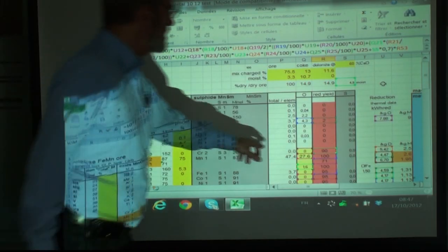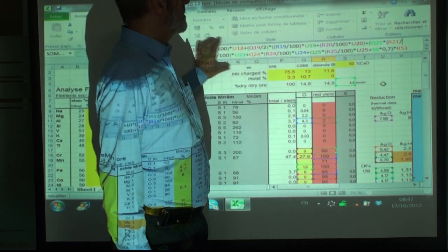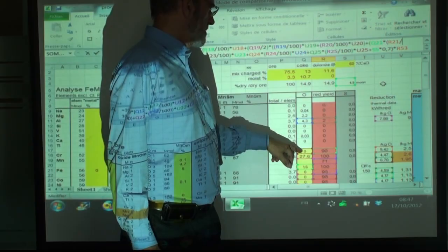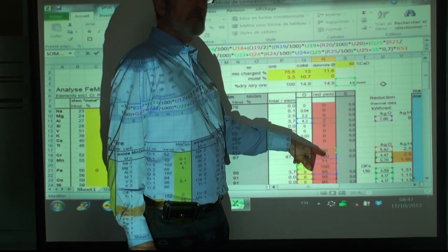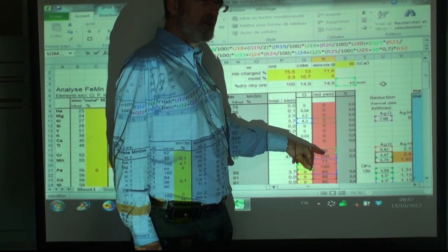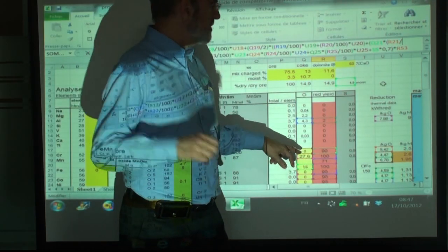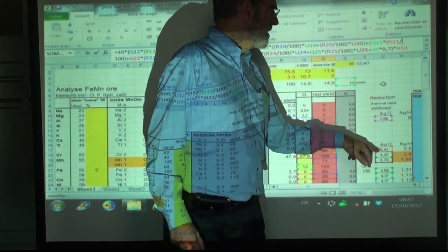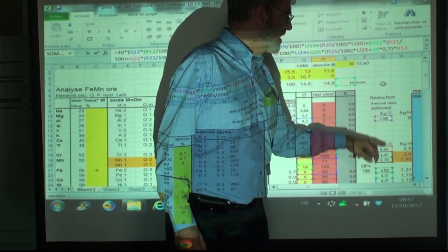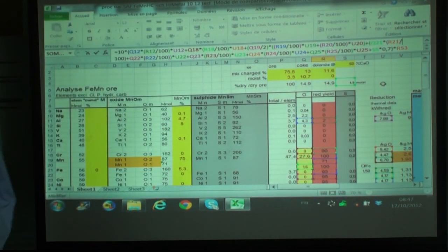You understand the principle of this formula? All other factors before is just multiplying the kilo oxygen by the reduction yield, which gives the real kilo oxygen removed, and you multiply by the heat and by the column giving this heat per kilo oxygen. So this is the reaction heat.